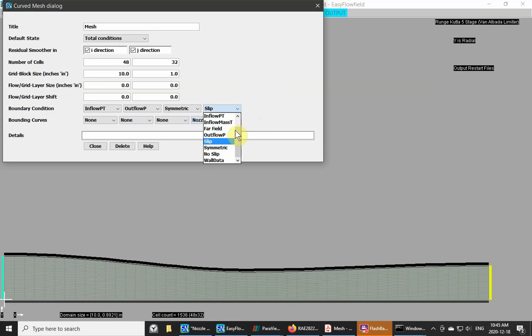And again, you can use quite a few boundary conditions in the grid. In this case, we're imposing total pressure and temperature on the inflow, and a specified static pressure on the outflow, but this will be overridden by another dialog with a different state condition.